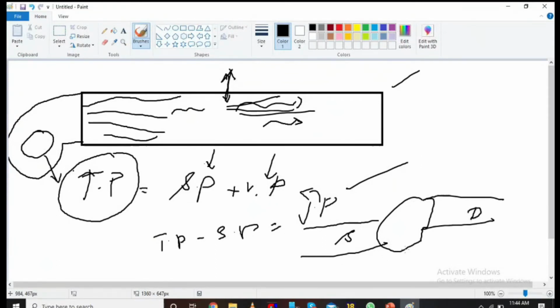Okay, now what happens? You have a centrifugal blower here which is sending air. You are measuring velocity pressure here. In case I am telling, you will be measuring like this, measuring total and minus it. So pressure is acting in the direction of the flow. Even if you measure here also, flow will be like this only. For velocity pressure it is always positive because it is always exerted in the direction of flow.